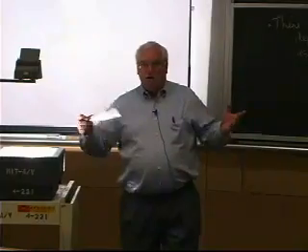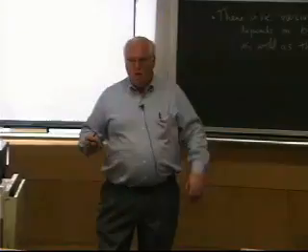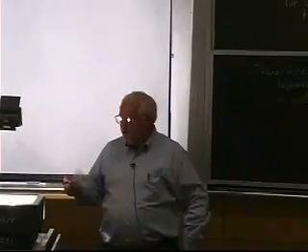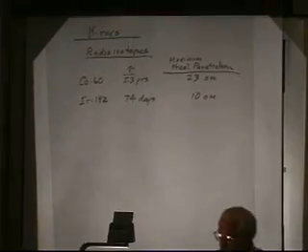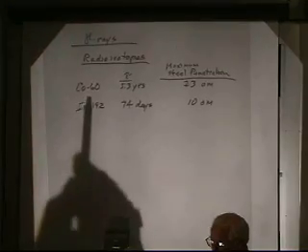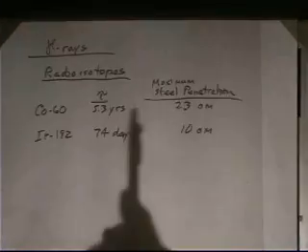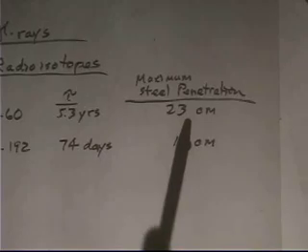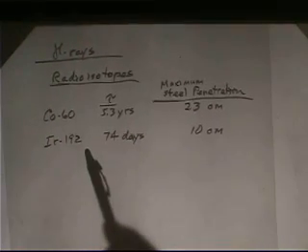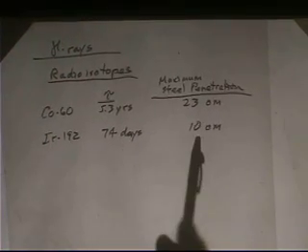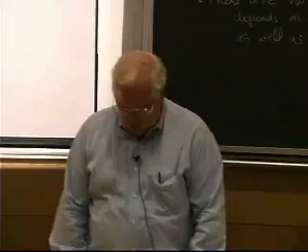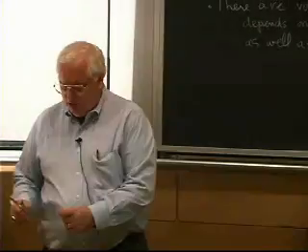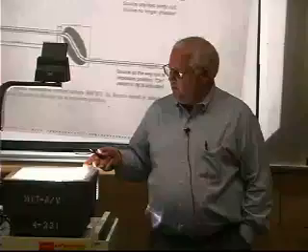In the field, you can't take a linear accelerator with you. They're just not exactly portable. You also can't just plug one into any old 110 volt outlet. You need lots of power. So in the field, we actually do use radioisotopes to give off gamma rays. Cobalt-60 is one, with a half-life of 5.3 years, and it'll go through about 10 inches of steel. Iridium-192 is more commonly used because it'll go through 2.5 inches of steel, which is about all you usually need, but it has a half-life of 74 days. So sometimes it gets a little pricey to keep replacing it, but if you have a big enough business.